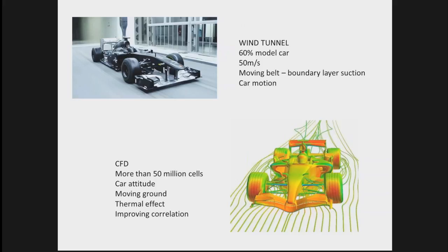But the air coming from the fan will hit the moving ground with a certain relative speed to start with. So there is a boundary layer created, and there is a complicated system sucking the air. So the air is really close to the ground with no relative speed to it, effectively like in the real world, when the car is moving and the ground is stationary, as well as the air around it.